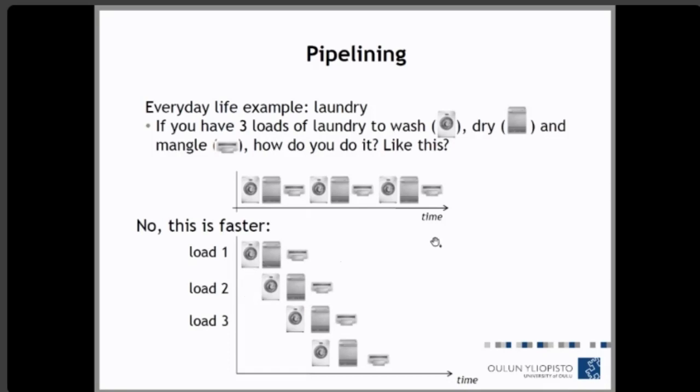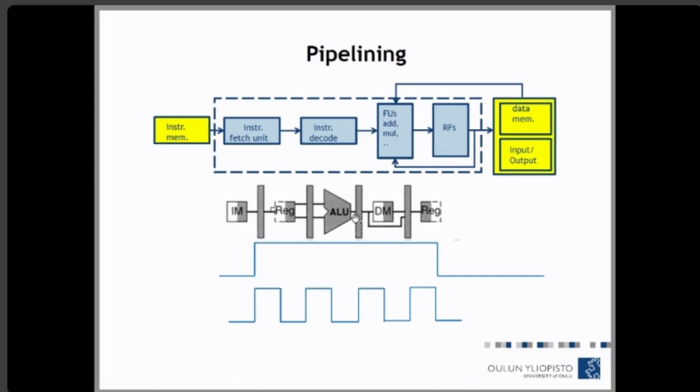As we increase the stages of the pipeline, we increase the amount of parallelism that can be achieved within that pipeline. So instead of having a very long clock period, and a very long clock period means a lower clock frequency, instead of having, let's say, a CPU with 100 megahertz, I will have a CPU with 400 or 500 megahertz, four times faster, and now I can do things multiple times faster.